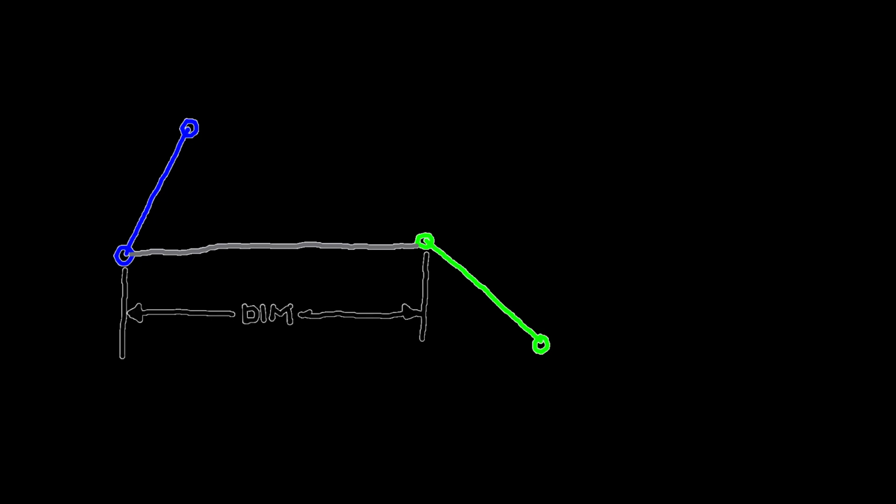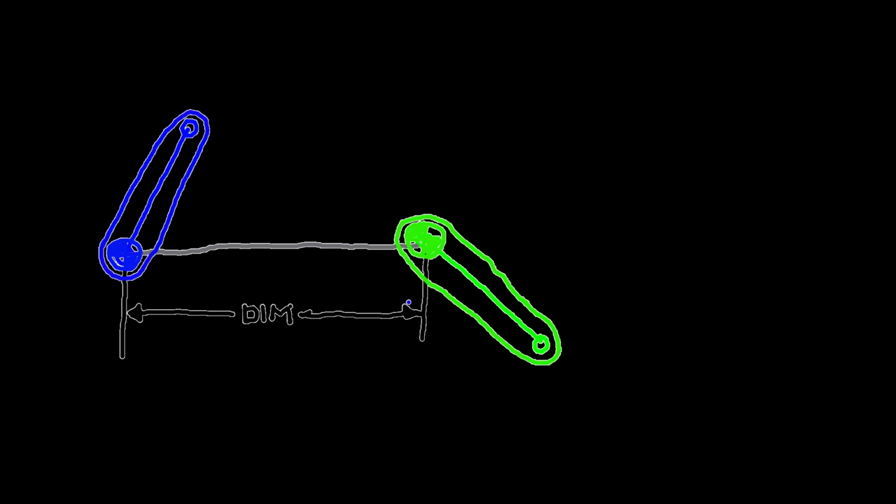However, your model needs 4 attributes before you can begin to build them. A green kinematically defined line with 0 degrees of freedom, a blue undefined line with 1 degree of freedom, any line joining the previous lines, a dimension defining the length of the linking line, this is the gear pair center distance, and pin joints must share the same coordinates as the linking line.